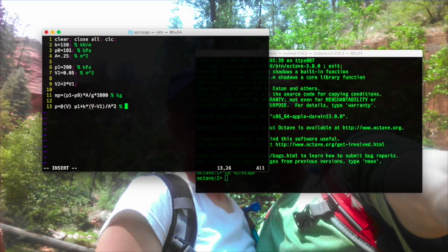So this is a volume, it's going to have units of meters cubed. And this is going to have units of meters to the fourth. So this is going to have units of 1 on meters. I already have kilonewtons per meter here. So this is going to be kilonewtons per meter squared, which is a kilopascal. So that's exactly what I want.